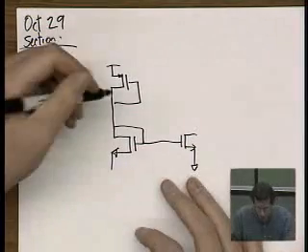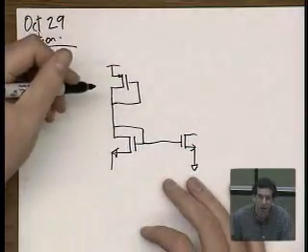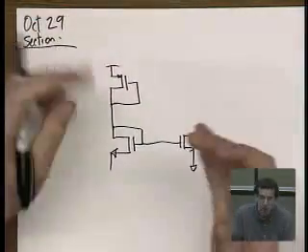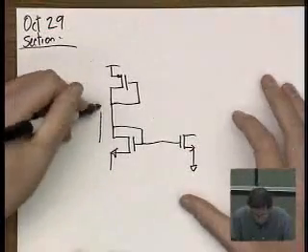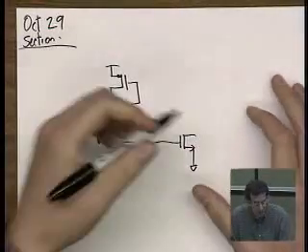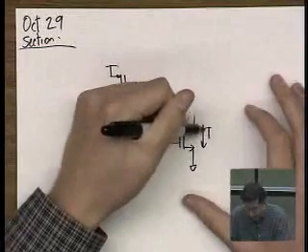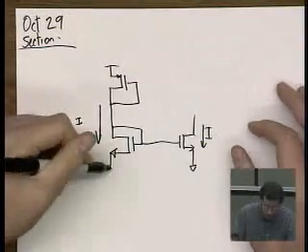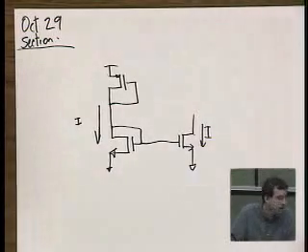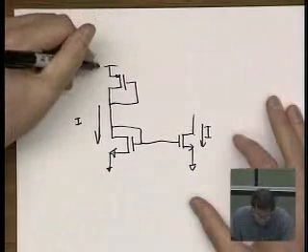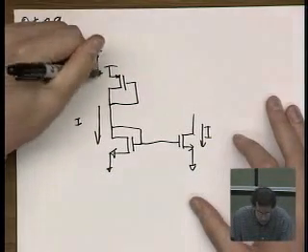Diodes take a lot less area than resistors, and you size them such that you get the exact right current flowing through this. You get your desired I, so therefore these output devices have desired I. Under the parameters of the first project, that was a good thing to do because diodes are very small area. Now what happens, however, is that now this VDD is going to change a lot.